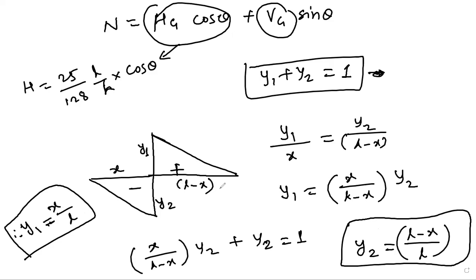So further part we will discuss in next class. Now there is nothing more, only drawing the ILD. You know the equations for N and S, and you have the value of VG, that is the ordinates y1 and y2. You have to multiply them by sin or cos, and the value of H by cos or sin. Refer to the equations of N and S: one has cos, one has sin, and vice versa. So we only have to multiply y1 by cos theta or sin theta, or y2 by sin theta or cos theta. The remaining diagram is as it is.